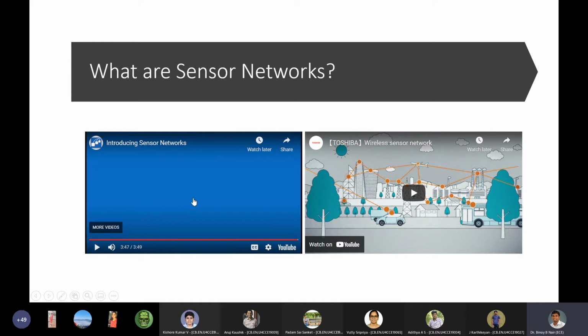The idea of multi-drop is like the lights people usually set up at Deepavali, the rice lights. You have seen those, no? There is one long strip and small lights all over the place. How you connect them is using this same technique. You just tap the live and the neutral, connect a small LED bulb there. Pick up the live and neutral, connect a small LED there, and so on and so forth. So basically you are connecting so many of them in parallel. The same thing is happening with RS-485. Two wires will be running throughout the length, and you are basically tapping them to connect more and more devices.